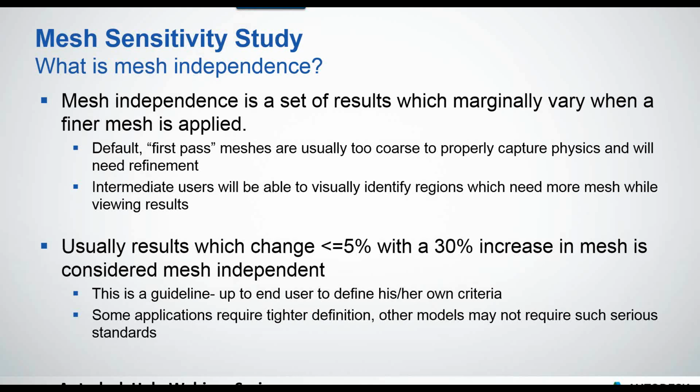So, when you have geometry and hit auto mesh and run, it's probably too coarse, chances are. And it really depends on the granularity and the quality you need too. Different applications are going to have different mesh requirements. If I'm trying to do a verification study or match experimental data of a pump or something, I'm going to have to put more effort and time into it. And just one note, intermediate users, people using the software a while, definitely the support folks will be able to identify an area which needs more mesh based on the results.